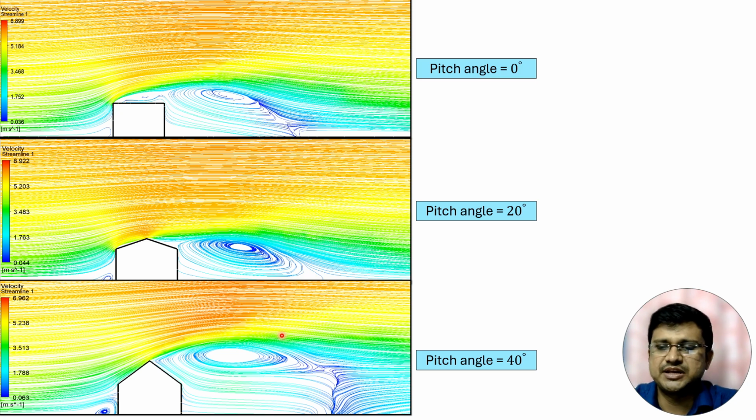So this phenomenon is very important, because when wind separates out from the building model, just after the separation point, vortex will be formed. If we look at the velocity distribution, the red color is where wind velocity is high, and blue color is where wind velocity is low. So in this particular zone the wind velocity is quite high, and in this zone where vortex is formed, wind velocity is actually less. Here also wind velocity is very less.